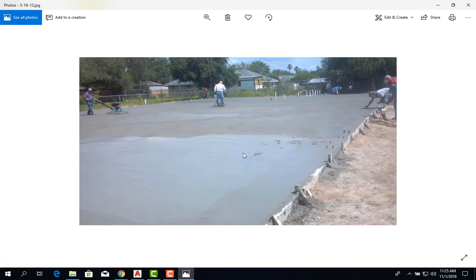Okay, so here they already poured, and now you see the finished floor height. I think the city required 18 inches above curb or 24 inches, I forgot. So this is the height that we needed, so in case it rains, the water won't go in, according to the standards of the city of McAllen. All right. So here they already poured, and they're just prepping it. They came back later and did the control joints with a saw, I think at like 2 or 3 days after they poured, and you can read about control joints in your book.